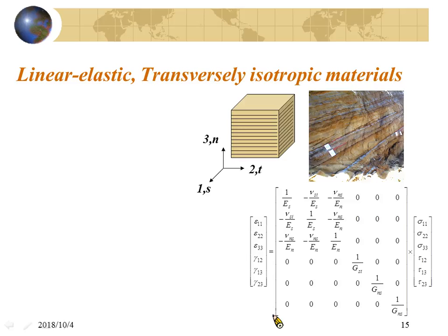Can you understand? Okay. So you will have 2 Young's moduli. You will have 2 Poisson ratios. How about shear moduli? You will have a shear modulus in the 1, 2 plane, and a shear modulus in the 1, 3 plane. The shear modulus in the 1, 3 plane will be the same as the shear modulus in the 2, 3 plane, and will be different from the shear modulus in the 1, 2 plane.